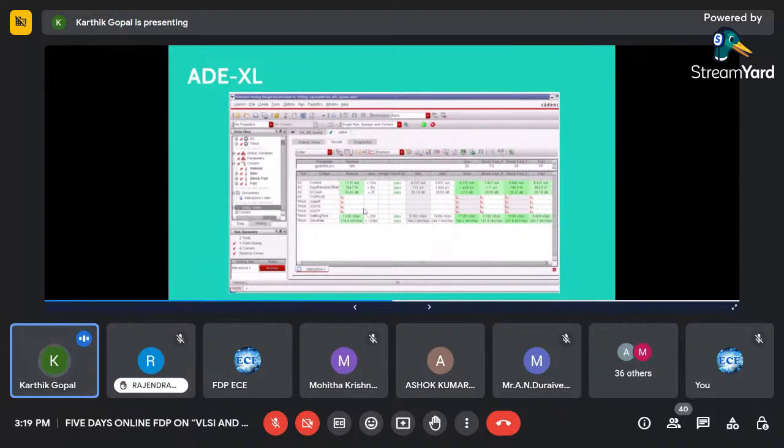That is the use of this tool. You can use multiple corners here, run, and check the result at each corner, so that you cover the whole wafer. Typically, if you design and send for tape out or manufacturing, the chips at the end will behave differently. So whenever we design the chip, it is done with all the corners, to check whether it is passing or not.